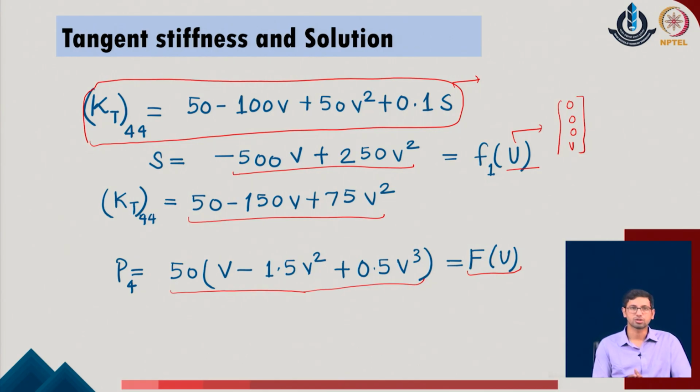So, what a user is necessarily trying to solve in a regular nonlinear analysis is the solution of this force equation, because this force equation is connected with this displacement field. If I take a small variation in terms of the d of P4 value of the system, I realize that this could be written as del f upon del v into dv for the given system. This del f upon del v is the same as the tangent stiffness of the given problem. So, we are eventually trying to solve this part of the problem to obtain the solution of the nonlinear problem.